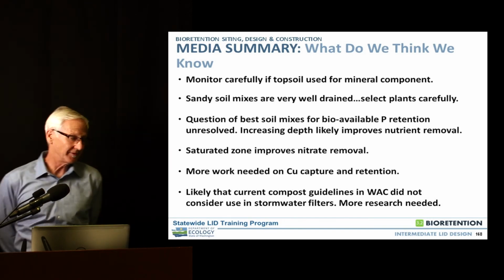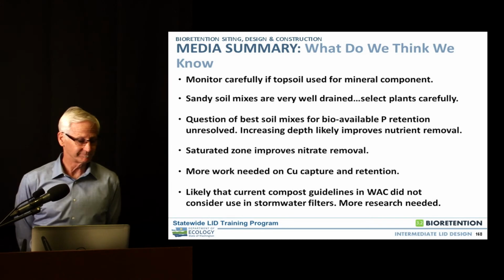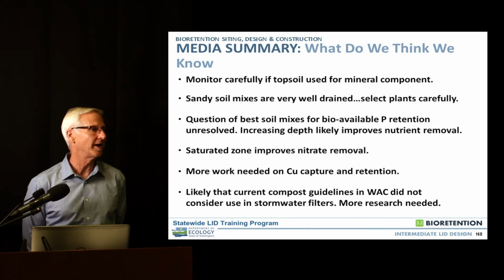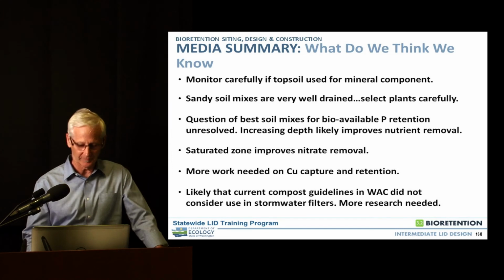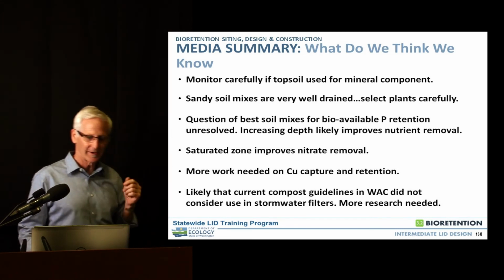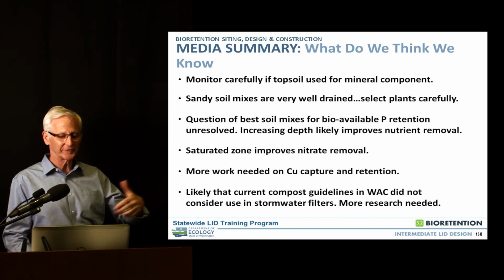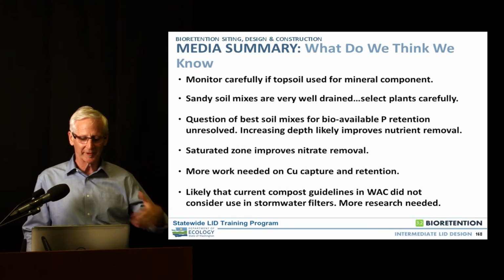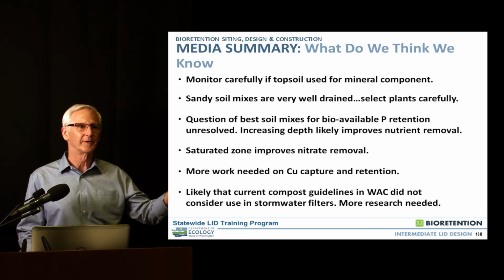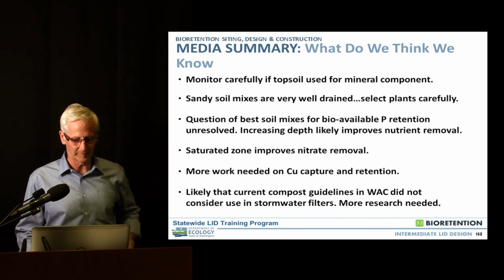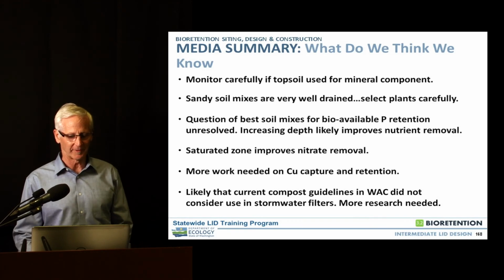If you're using these sandy soil media, which most people are now, the sand and compost, they're very well drained. So you have to be careful about your plant selection. We've had numerous cases where, using these sand and compost mixes, it drains quite rapidly, you put in plants and they die because the system is draining so rapidly. So you just have to work with your plant folks carefully on the right selection.